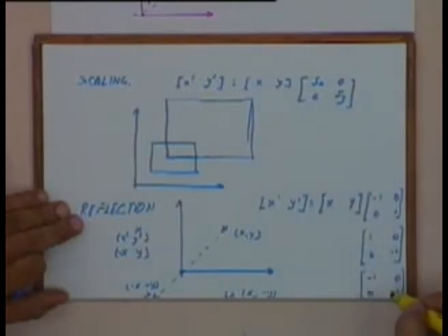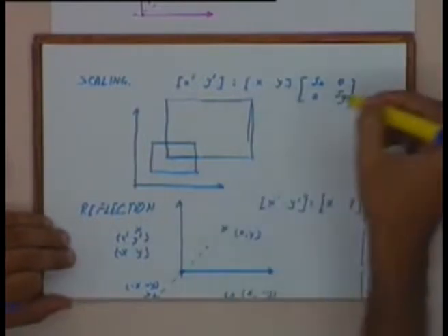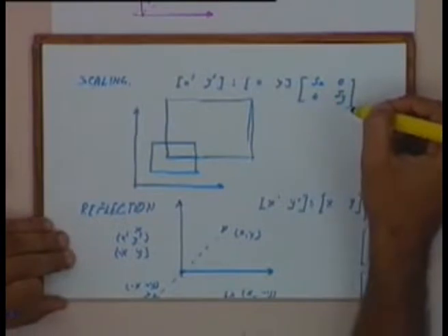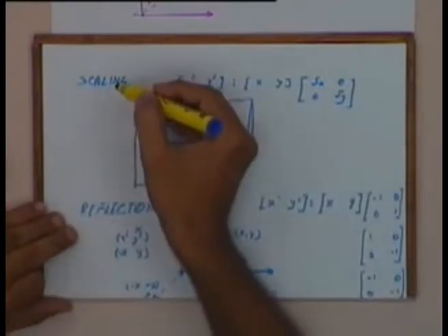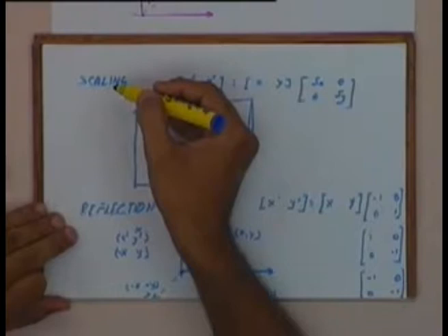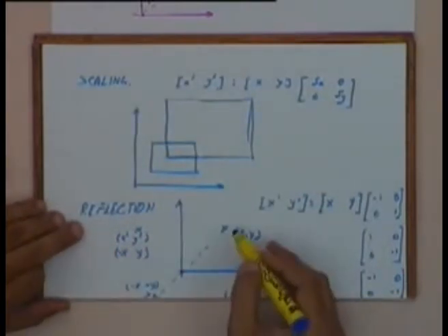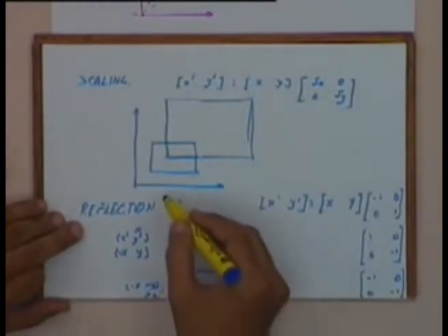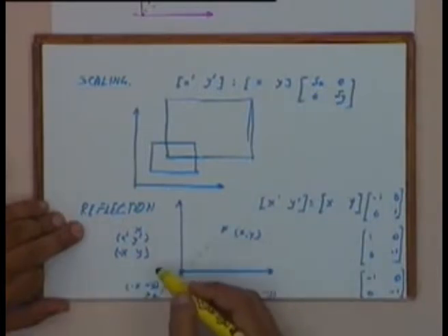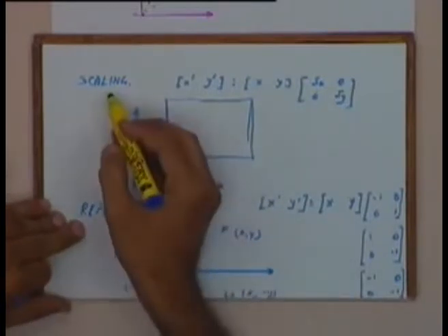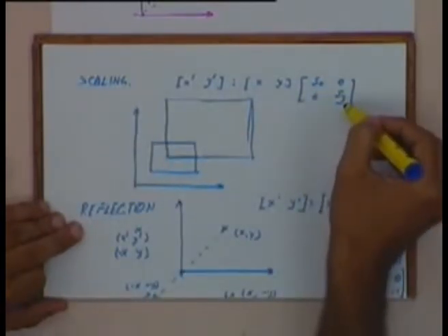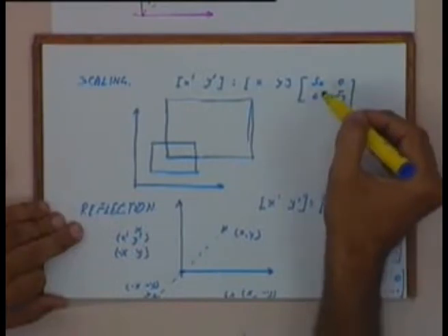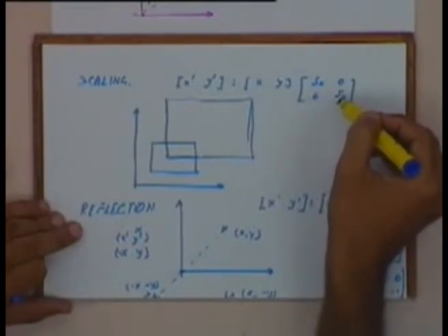Similarly, the other two reflections can also be captured as scaling operations. So reflection is nothing but a specific case of scaling. Whenever we want to reflect a point or an entity about either the x-axis, y-axis or about the origin, that can always be obtained by scaling by having the correct values of Sx and Sy. Either one or both of them will be -1.